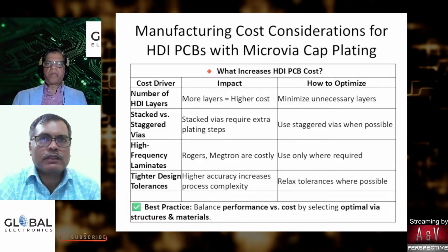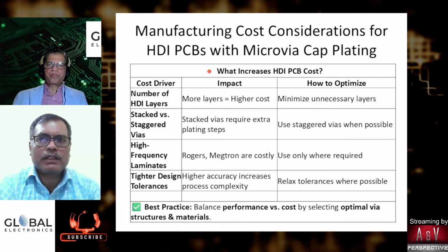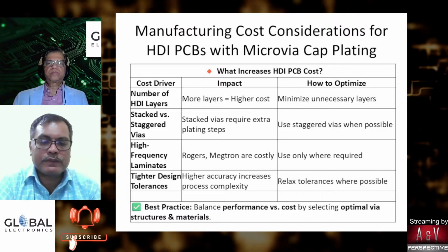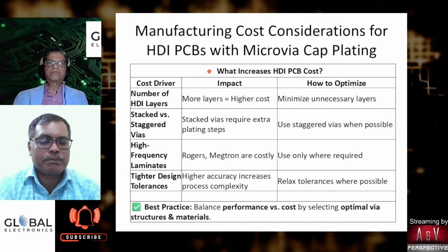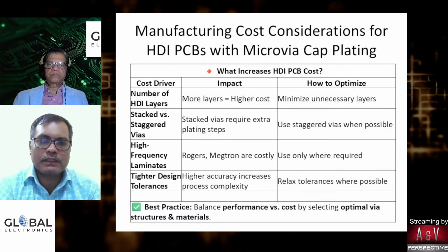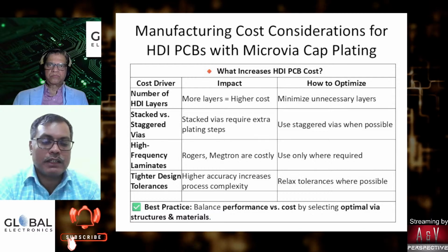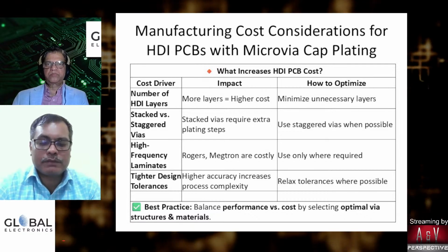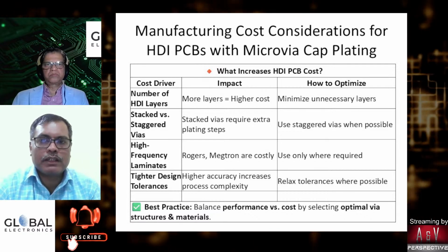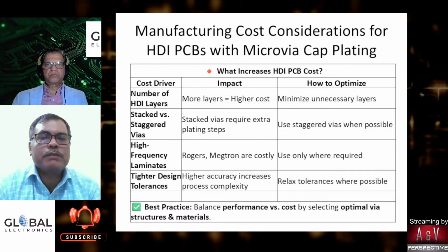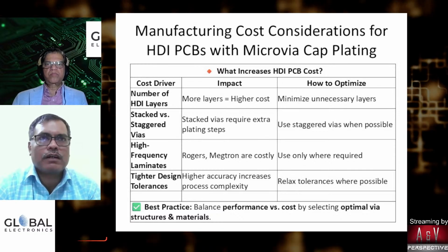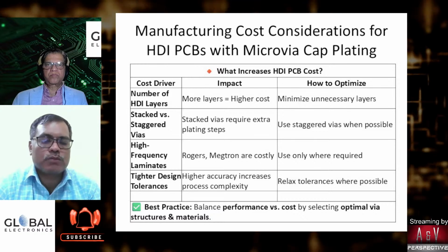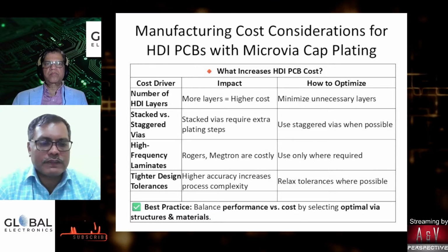It is done by the American military agency, approved as per their requirements, and we have to submit the coupons. It is a process-related approval, as well as material approvals, and in every aspect they will verify and approve as per the PRF 31032 requirement. So your PCB becomes a MIL grade PCB. That is very important. Nowadays all defense applications will have MIL grade PCB approval. That is the first and foremost. So that is about the universal defense applications.